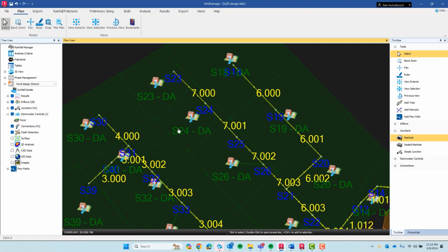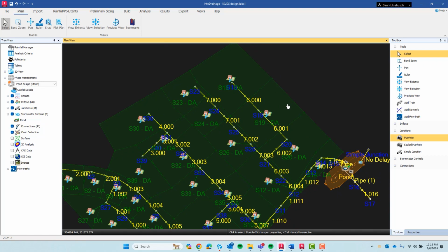You can snap your manholes to where your manholes are, and you can snap your pipes to where your pipes are. So you're not having to get just an estimate. It can actually be right over your line work. So when you go back and forth importing and exporting changes, sizes, materials, and such, all that stuff will stay in the same location and be correct in Civil 3D and in Autodesk Water.